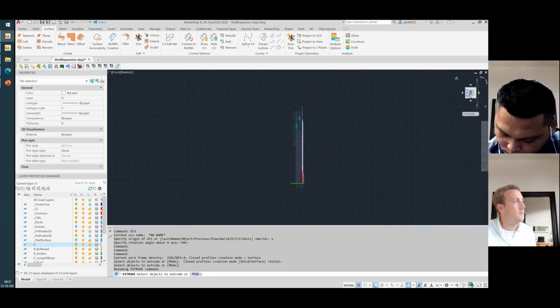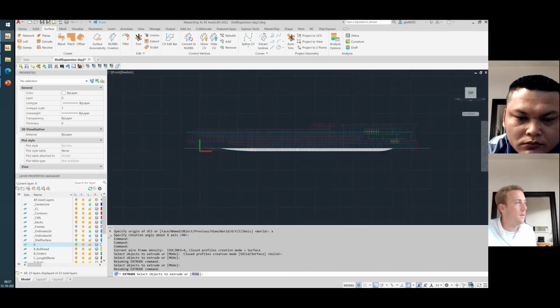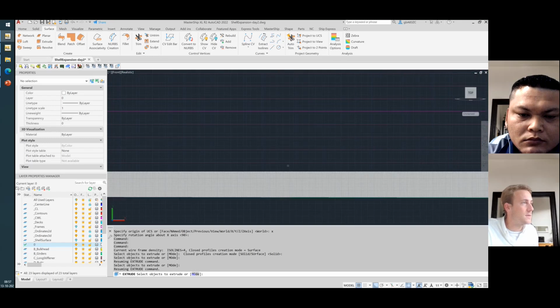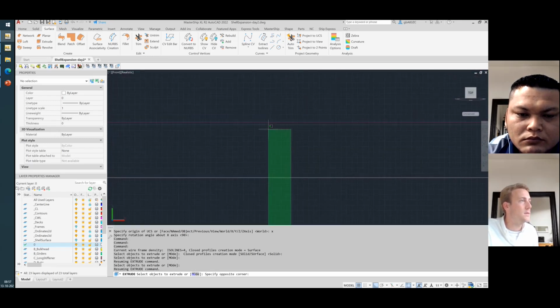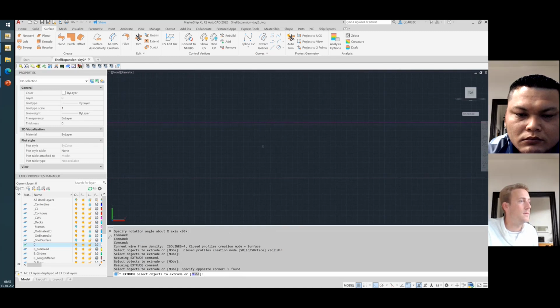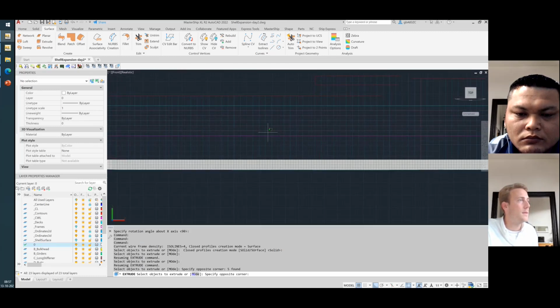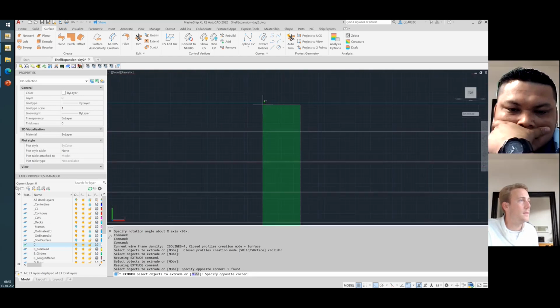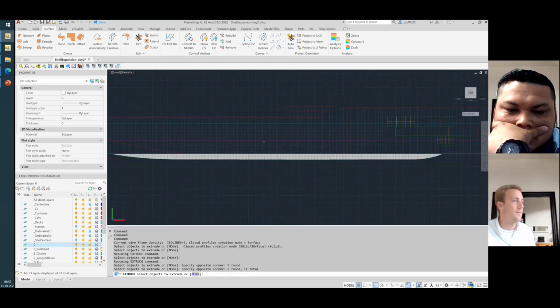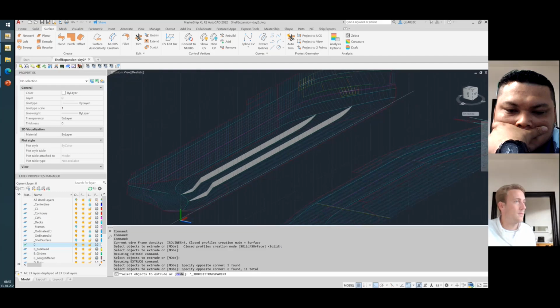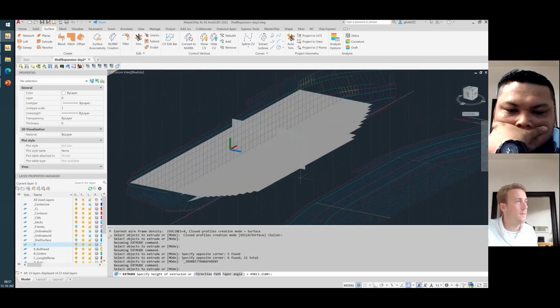Okay. And then we are going to extrude those longitudinal stiffeners. So I go to this view. And I select all the stiffeners. Let's see, here's one stiffener. And those are stiffeners. I do OK.